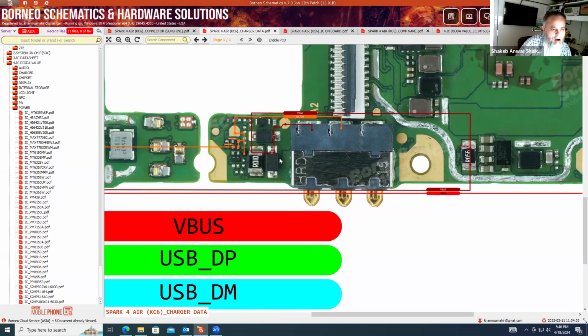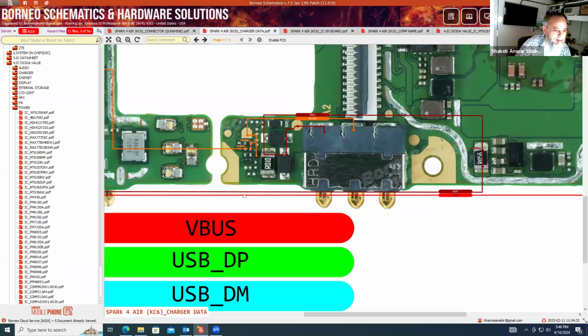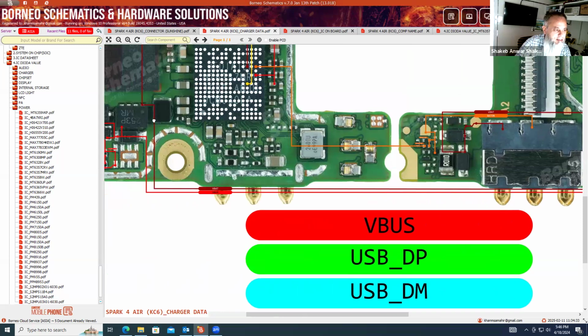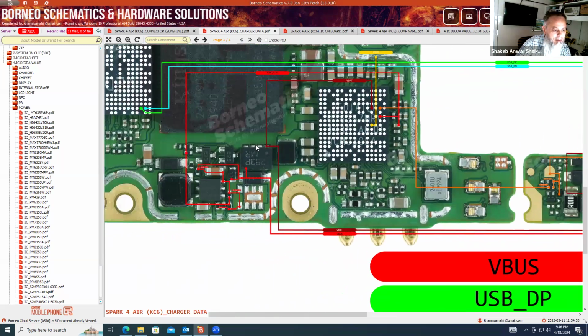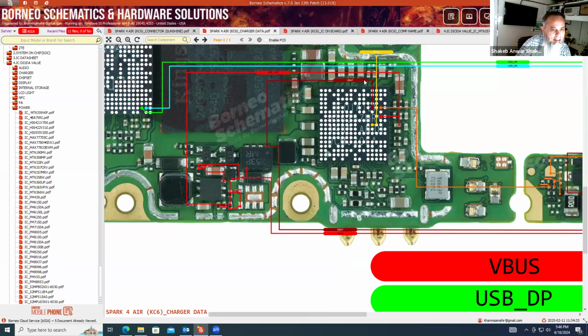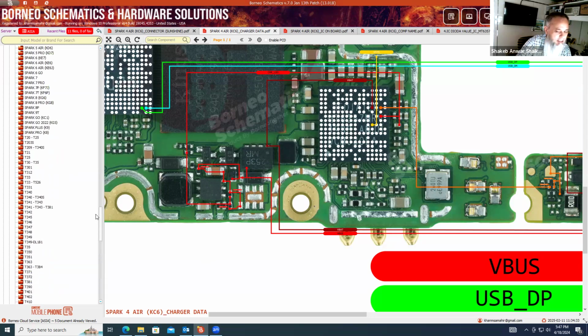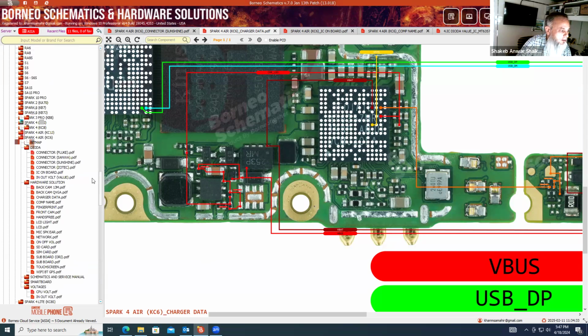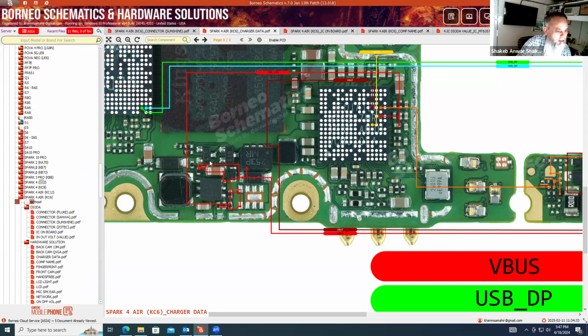Okay, so how the voltage is coming to this point, that is more important. You have your VBAT line, which is connected like this. It is connected to this one particular component over here, and then it is coming to this IC. Now this one is used for switching purpose. This is a transistor. This is also a transistor. This is also a transistor. How does it work? You will have to see it in the schematic. So that one I will try to take tomorrow in the schematic.